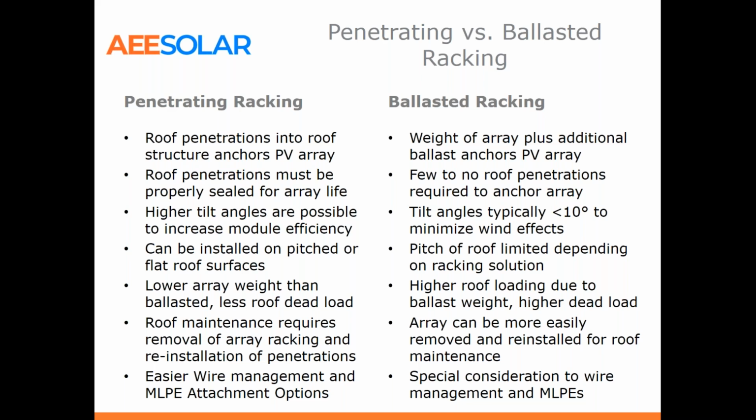Typically 10 degrees or 5 degrees is used to limit wind effects. The 15 degree does need more ballasting. Again, we mentioned that 5 degrees or less is the limit on the roof pitch. Also, there are some height limitations, of course, as the wind keeps going up the higher you go.